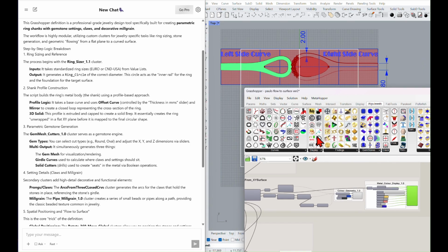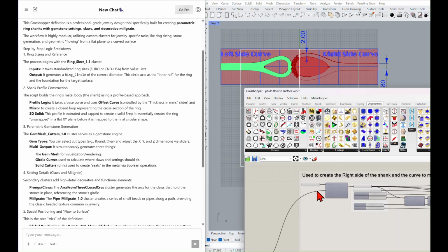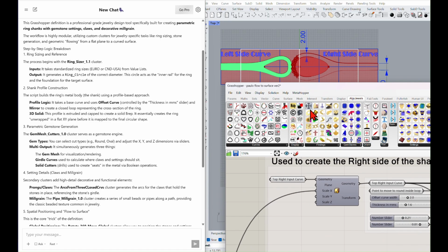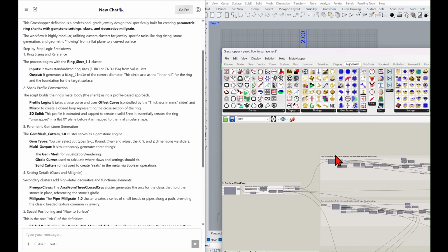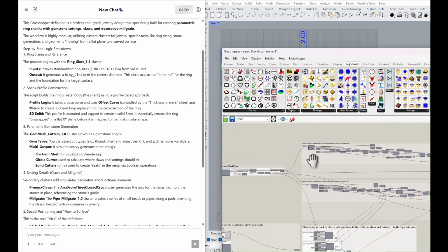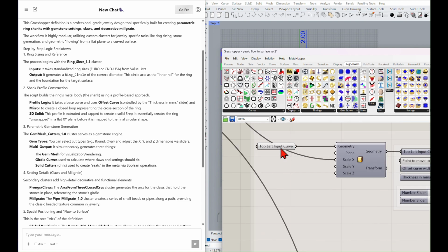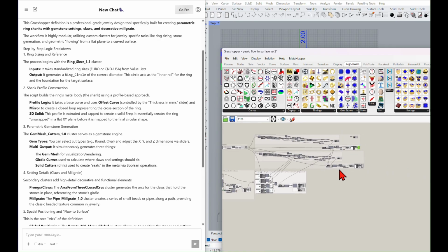And we're doing the same on the opposite side. So we have a right side used for the right side. We create this curve. We mirror the curve. We close the curve. We extrude the curve up, cap it, and then we find this curve, extrude it, cap it, and Boolean difference for the left side and the right side. So we're using the left side and the input curve on the left side, right side.